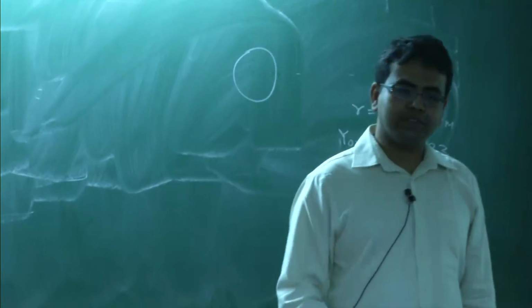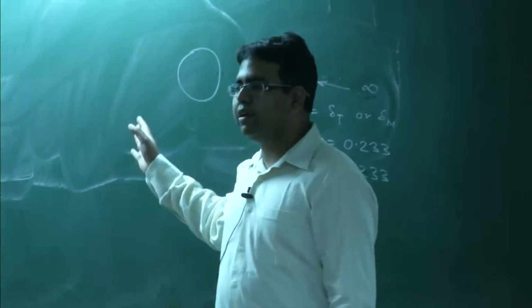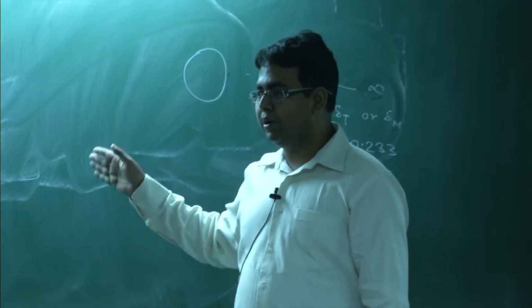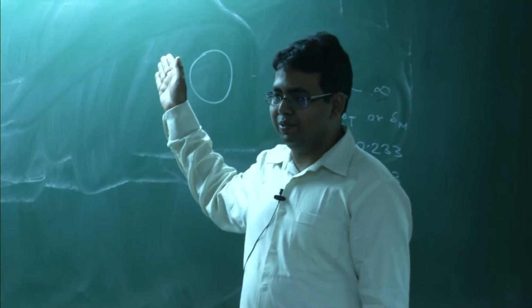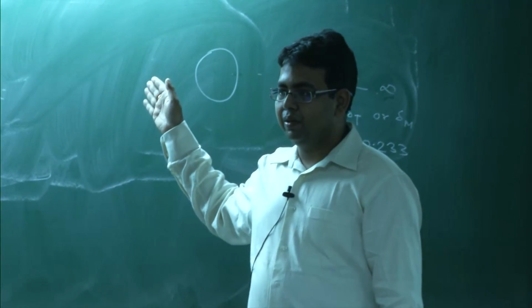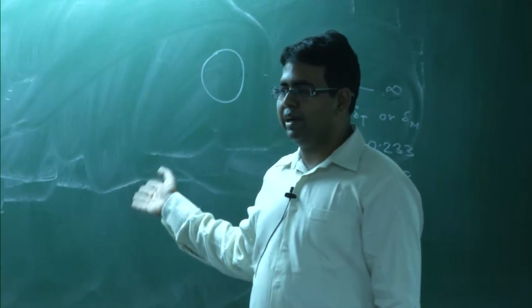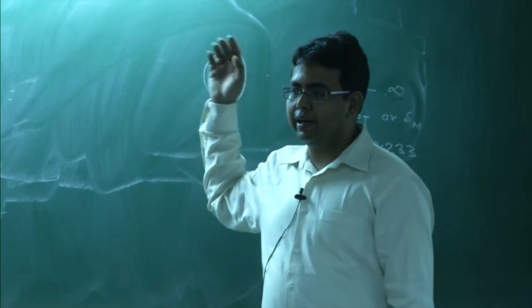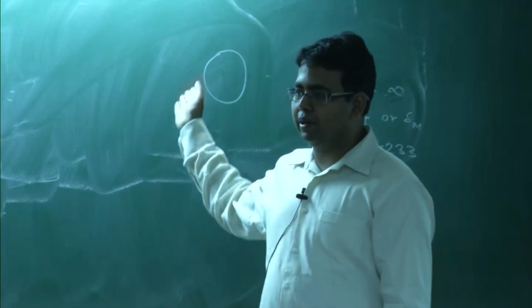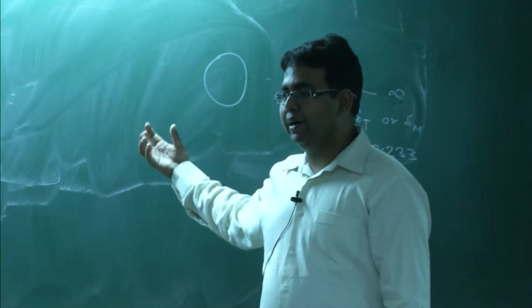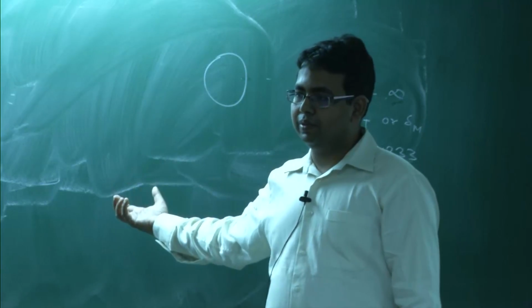So, turbulent dispersion is basically you have a turbulent flow field and then the droplets are there. Okay. So, the droplets will try to catch up with the turbulent flow, right. So, when you have the smaller diameter droplet, they find it very easy to cope with the underlying turbulence. So, they just follow the turbulence. Okay. But if you have larger particles, they cannot. Okay.